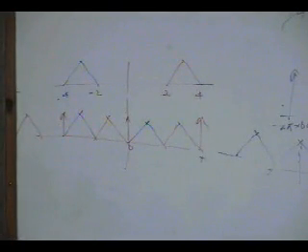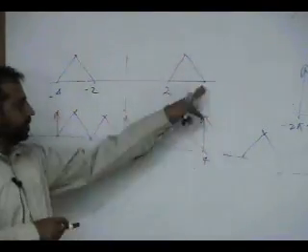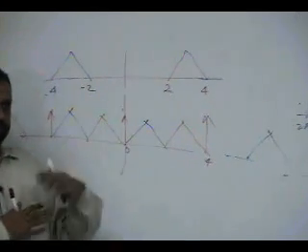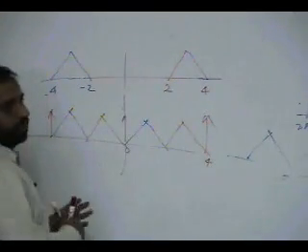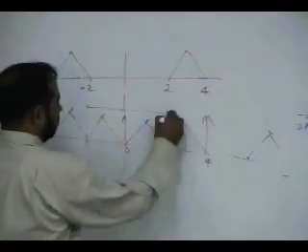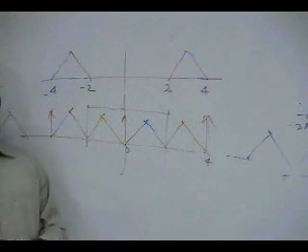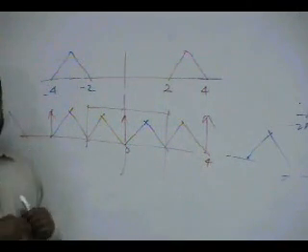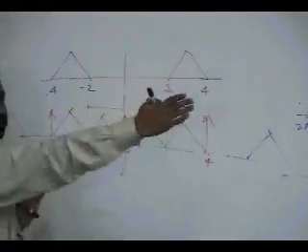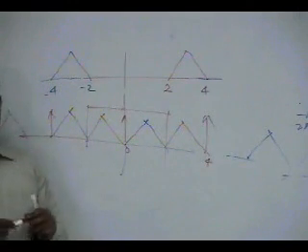There is no aliasing. Though you are not obeying Nyquist, by playing with this, you can sample it at a slow rate using a low complexity converter, and you can move it down. This is good. You can move it down, and now you can filter it out. You say, I only need this much. And then you further bring it to baseband. Usually we want to bring every signal to 0 frequency in communications. This is a trick which is used.